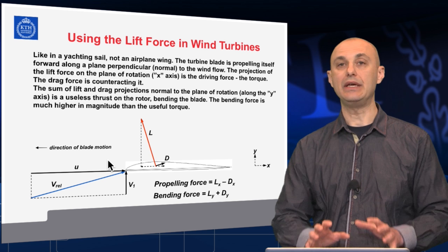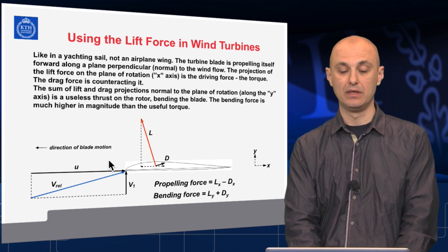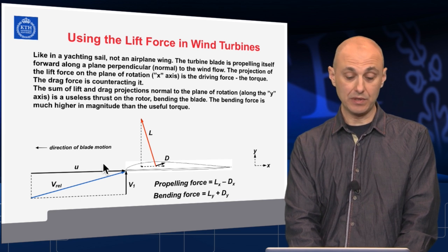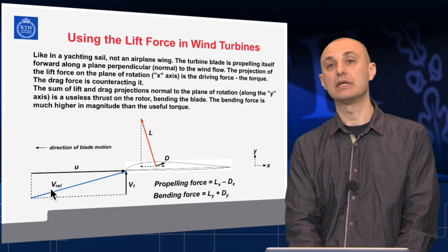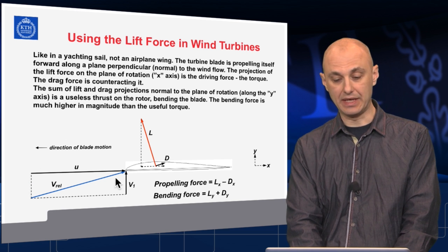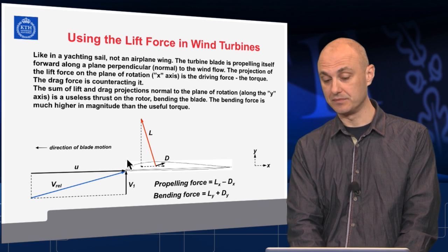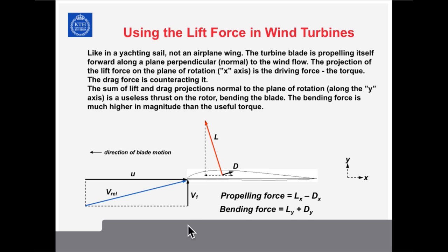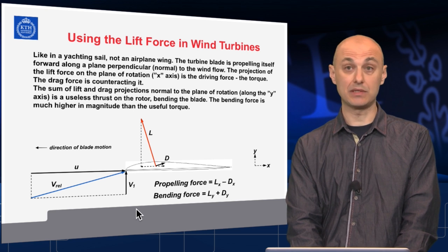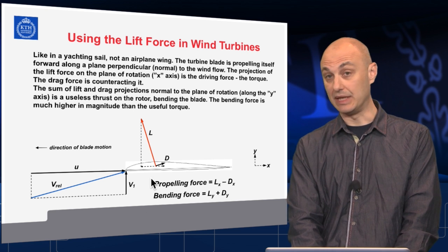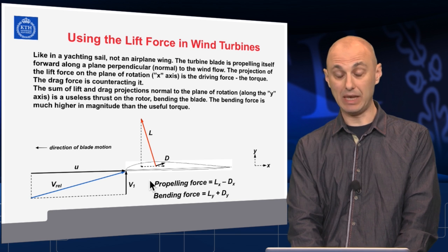Even if the air is completely standing still, the fact that the blade travels through air means that there would be a relative velocity of air u towards the blade. The real wind comes from here, directly towards the belly of the blade, or the pressure side of the wing profile. And it's comparatively low speed wind compared to the speed of translation of the blade.